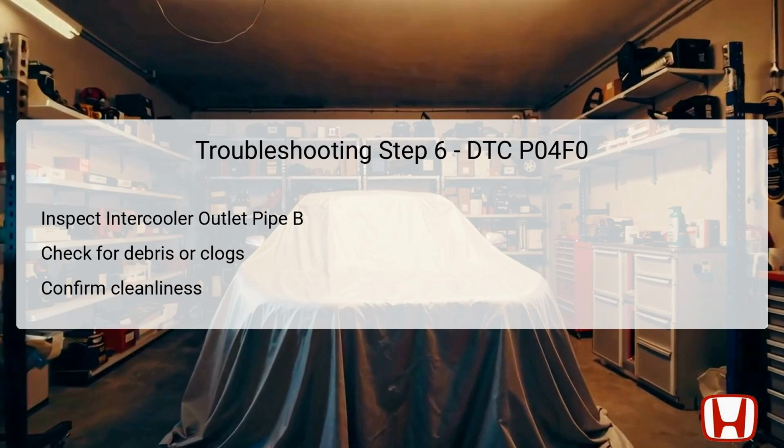This port is crucial as it directly connects to the intake air system and can significantly impact engine performance if compromised. The inspection should ensure that the pipe is free from obstructions, which could hinder airflow or vapor circulation. Ensuring this component is clear of any debris is critical for the efficiency of the entire evap system, as it feeds vapor to the engine for combustion purposes.